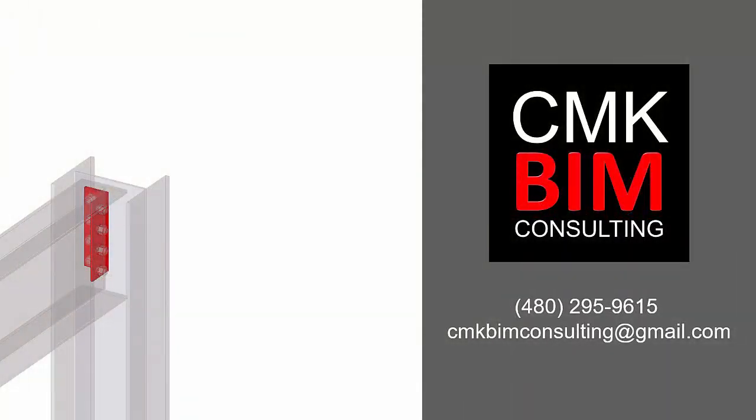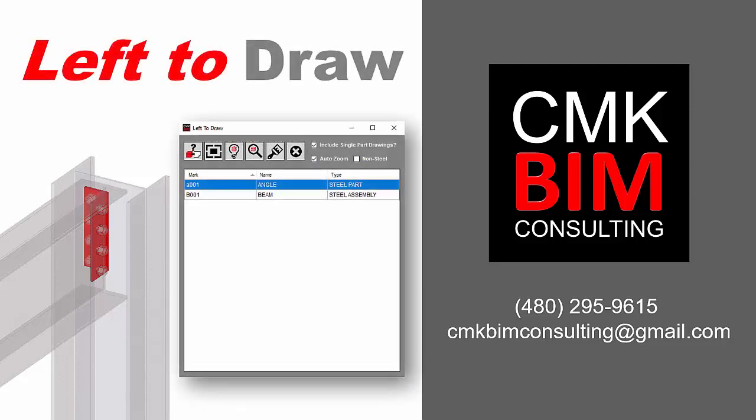So here at CMK BIM Consulting, what we did is we created a tool called Left to Draw. And what this does is it easily scans the objects in the model and then scans all the drawings in your drawing list, and it automatically lists out all of the different single parts or assemblies or even cast units for concrete to tell you what things are missing, and it highlights those and then allows you to easily zoom in and find those pieces or assemblies or cast units that need to have drawings created. As you get those drawings created, you can whittle down and remove the items from the list to make sure that you've caught everything. So let's go ahead and take a look at this in action.